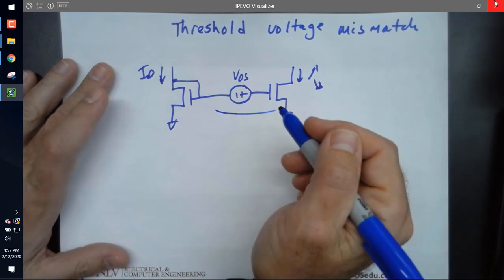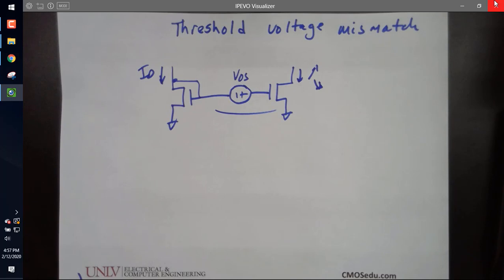So if I have a real design, simulators nowadays can actually build in the mismatch. They call them Monte Carlo simulators. They will put in different mismatches and look for imperfections in the circuit. So when you design a memory chip and you've got tens of thousands of sense amps, they will run a Monte Carlo simulation on the mismatch of the sense amps to see just how tolerant they are to mismatches and how well you have to keep the transistors manufactured. Because if they go beyond a certain tolerance, you start getting so many bit errors, the memory chips aren't useful.